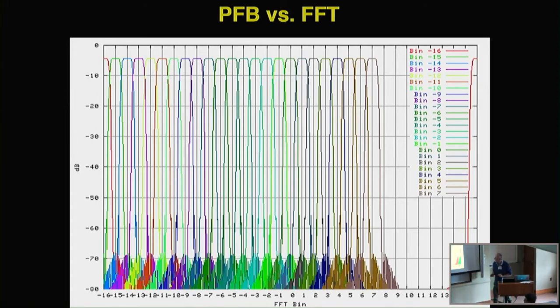Yeah, and each of these bins would only fill up to the extent that there's power in that band. Right, this is the response of the instrument, not the spectrum of the signal. A perfect filter bank would be what we call a brick wall filter, infinitely steep and flat on the top. That's kind of impossible. It kind of violates Heisenberg, but this comes really close.